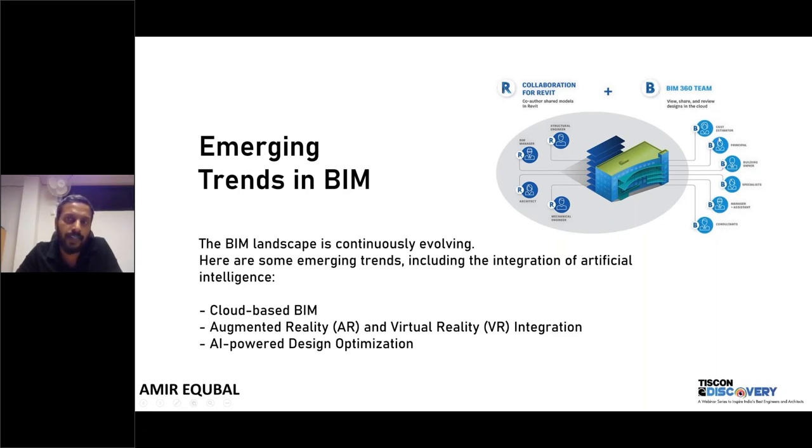And the other team, that is your cost estimator, building owner, specialists, and all the builders, all of those consultants, can access it without having the software. They can access it through BIM 360 on the cloud. They can view the model, they can make comments, they can have design reviews on the cloud itself. So that way it becomes real time. Also, it cuts down on the infrastructure needed to adopt BIM.